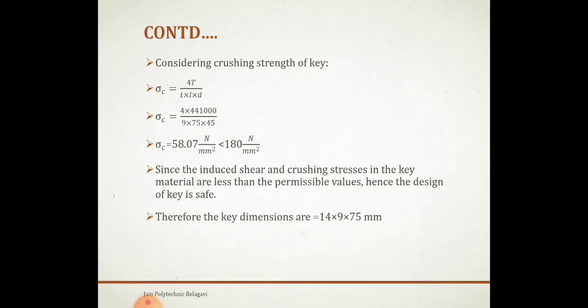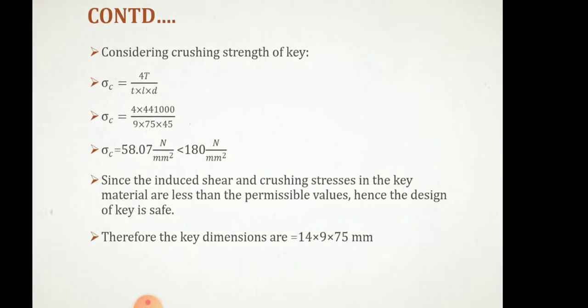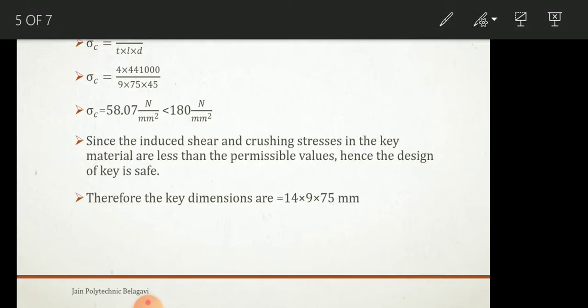And yes, therefore the dimensions of the key are 14 into 9 into 75, where 75 is the length of the key, 9 is the thickness, and 14 is the width W of the key.